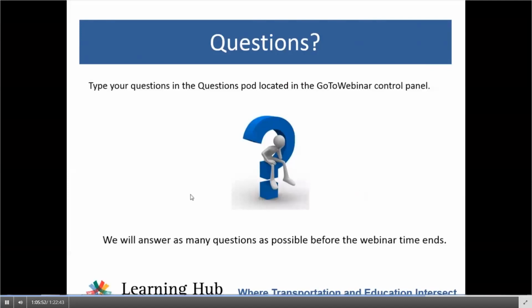The truck level of service method is looking at the quality of service provided by the roadway from the truck or freight shipper point of view. Does it meet the needs of the shipper, from the standpoint of whether their trucks can operate on that road? How reliable is the service provided on that road? How much does it cost to use that road? Things like that.